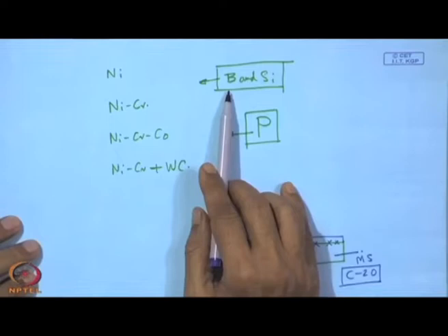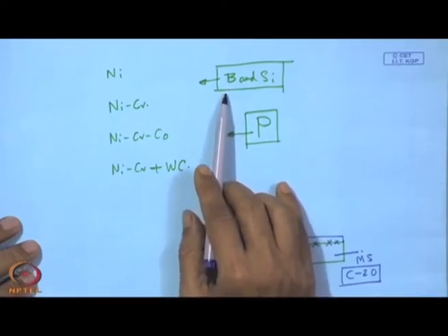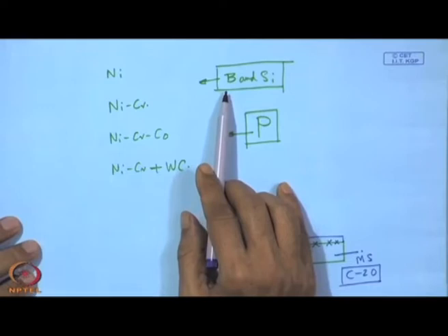Actually, we find that this is the very role of boron, silicon or phosphorus. What is their role? Number one, they are actually depressants; they depress the melting point, or they depress the liquidus and solidus points.